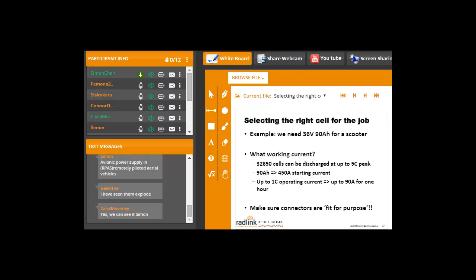But I would suggest that if you were running a scooter, once you've actually got past your inertia stage, your battery current will be significantly lower than 90 amps, probably only 20 amps even. So your battery will last easily 4 hours or more.